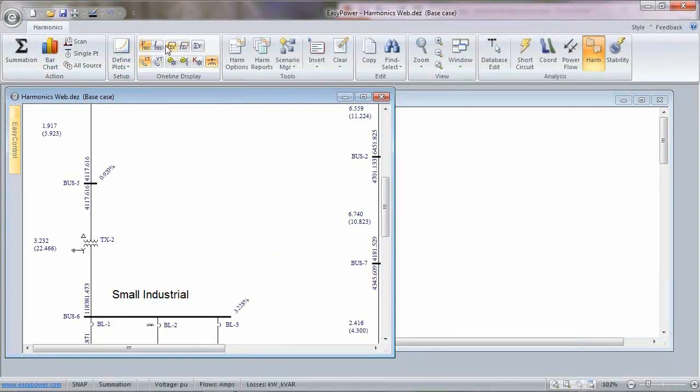Different forms of why we would have such a thing called V-sum, for instance. And that has something to do with a capacitor rating, where we want to do a summation of harmonic currents for the capacitor standard. I think it's capacitor standard 18 that you look at peak sum for looking at voltage stress on capacitors. So we have a number of topics we could talk about in the future again on harmonics, but that wraps up this one for today.